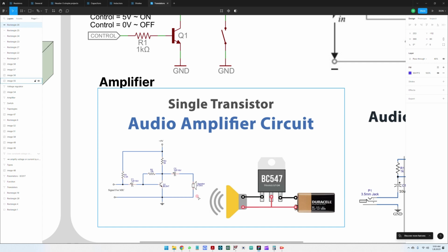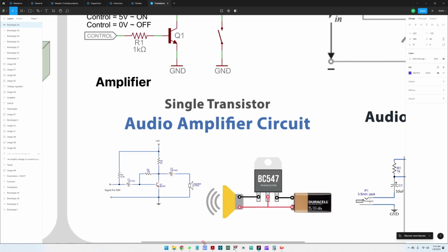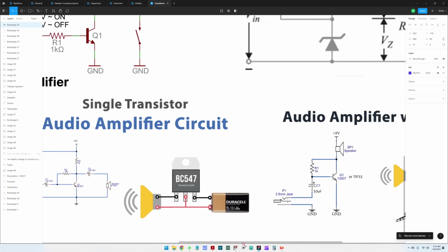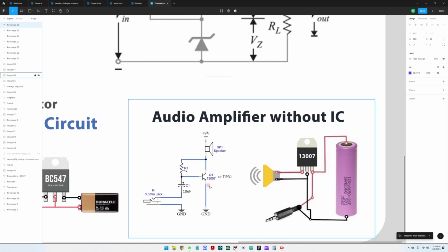Very important to note that driving the speaker, you don't need to have a DC component, otherwise you would break the speaker here. So we use an isolation capacitor here for the supply. This is quite a simple circuit. You can use a 9 volt battery to supply the whole circuit, and it would amplify the input signal to provide the correct output.